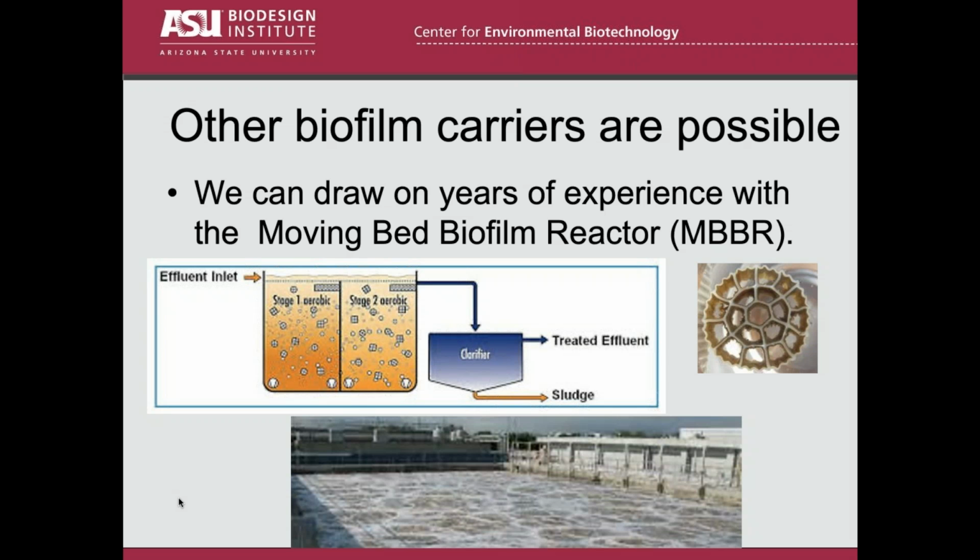You can see there's a lot of biomass inside these big pores of it. And then, you know, MBBR has been developed for aerobic treatment, so you can see at the bottom here we have the activated sludge. It's being aerated, but it's full of these MBBR media. So that's the idea.